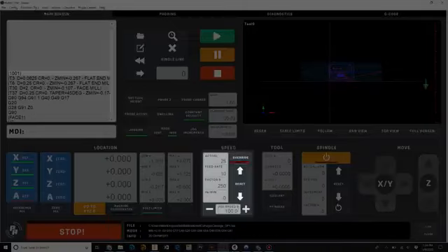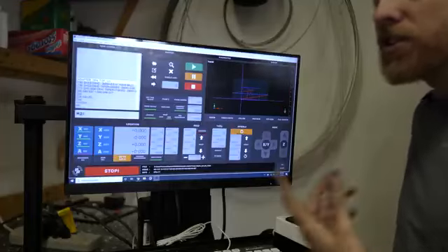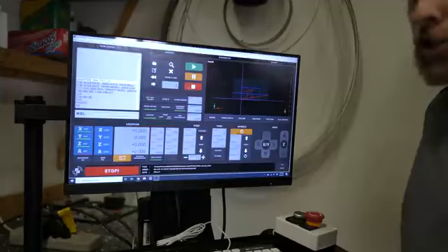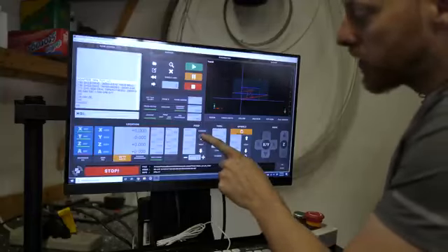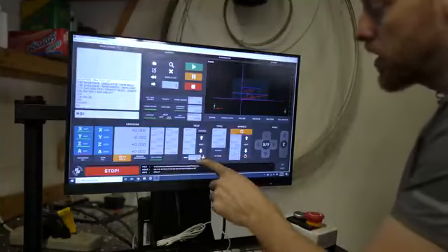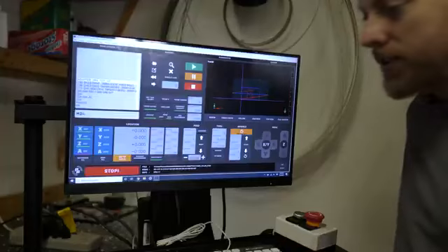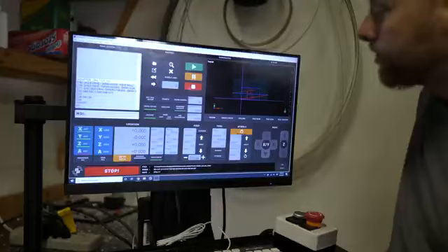And you get this nice override blinky button that is telling you your feed rate is set to something other than 100%, and it's a good warning. So if you happen to, you know, run it at 250%, you start the next operation that shouldn't be run that fast, this is kind of a warning. You also have some arrows if you want to just scroll up and down with that. Jog speed, this is how fast the machine is going to jog. Super helpful. I've set this to 2% because we're being really careful about moving the head back on the machine.